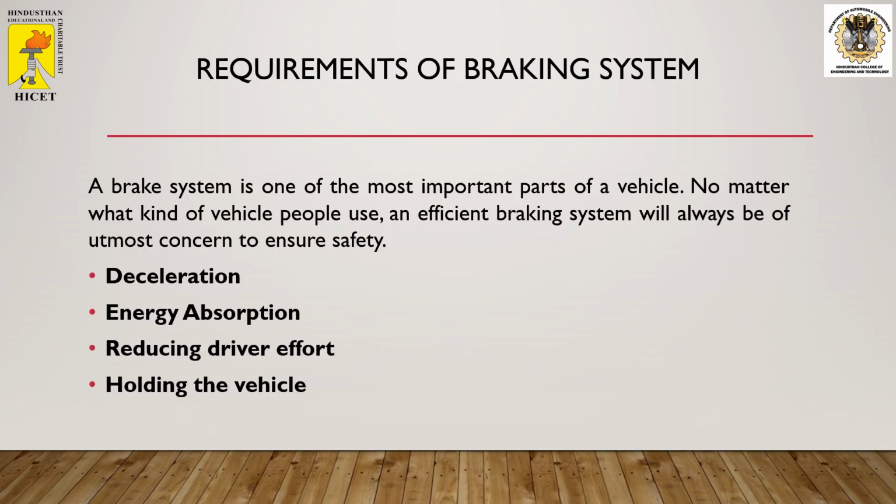As we are aware, the braking system of any vehicle is very important because it helps the vehicle to stop, decelerate, or hold in the right position. With this function in mind, let us understand the requirements of a good braking system. First of all, it should have a good deceleration ability. Irrespective of the vehicle speed, the vehicle should be able to slow down with the help of the brakes. Second thing is energy absorption.